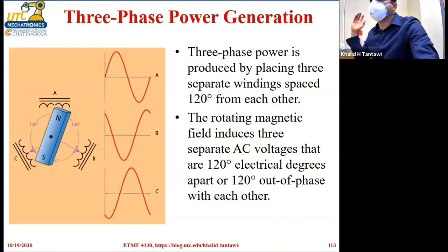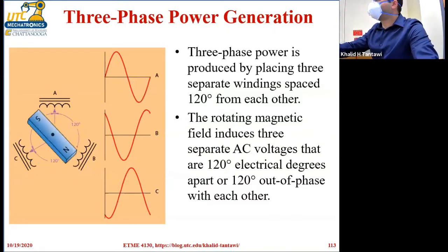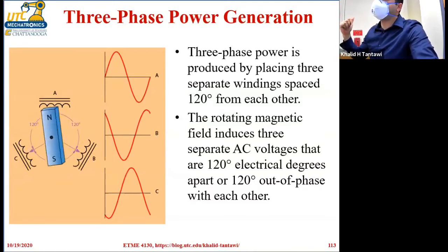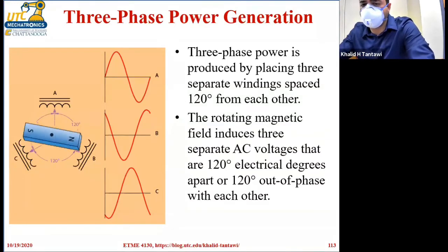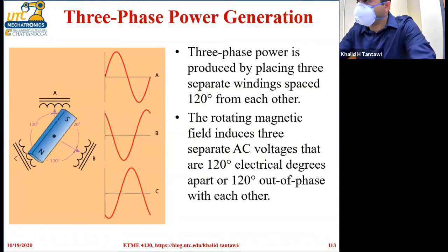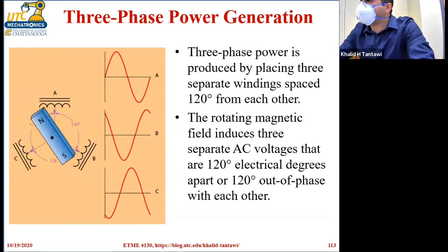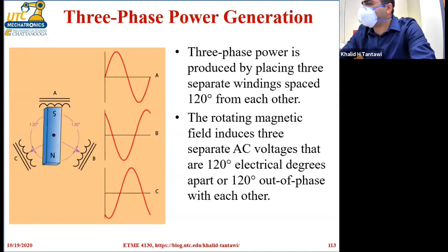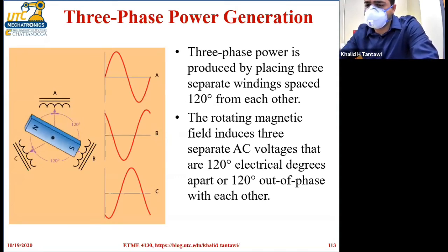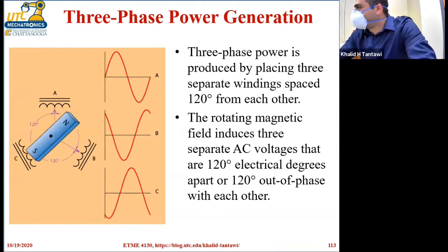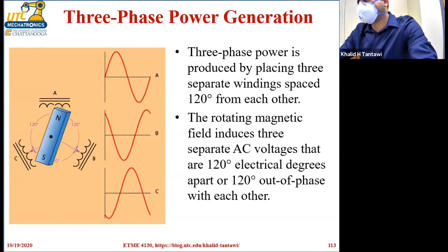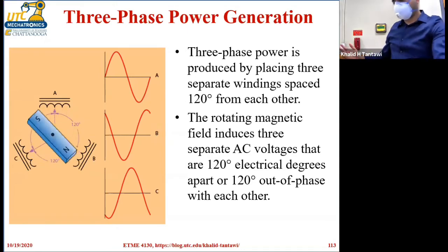They will just pass through each other, and one of them will be used to generate torque, while the other will just be causing heating and vibration. So it's important to remember that, if you have different frequency sources, the one with the lowest frequency is the one that will do the torque. But here in three-phase, remember, you must have the same frequency on all of them. This is a critical thing. But of course, they will be out of phase with each other.